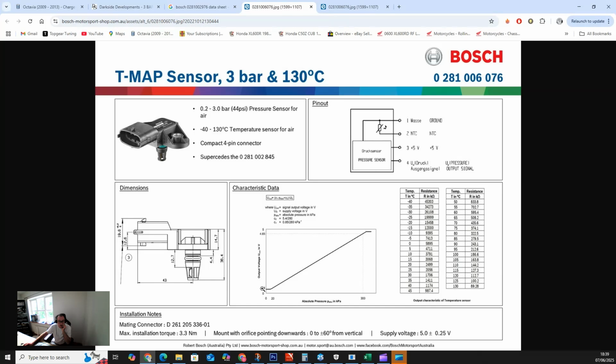Looking at the pressure here, I think that's 300 kPa or your 3000. And then your output voltage here. As far as the ECU is concerned, it looks at millivolts for these Bosch ones, and you're up to 4.65 volts here as your output at your 300. But as I say, in the ECU calibration, pointing at the screen like you're looking at me, we're probably about here, and that's kind of where I'm maxed out.